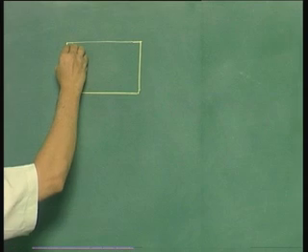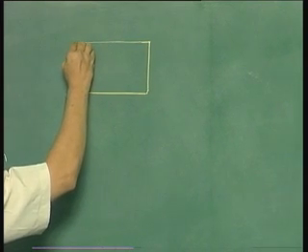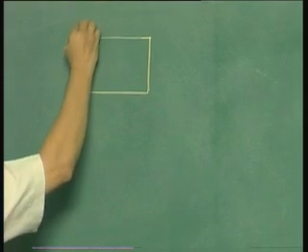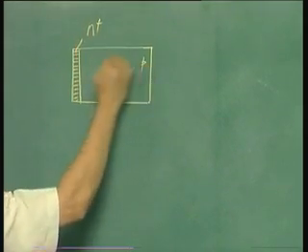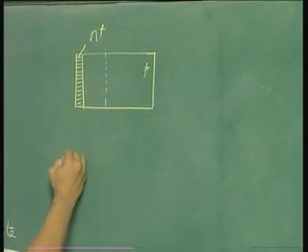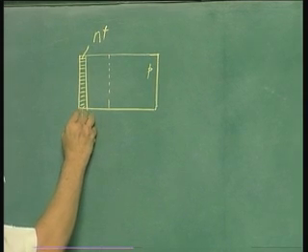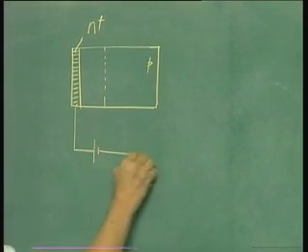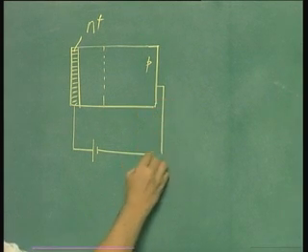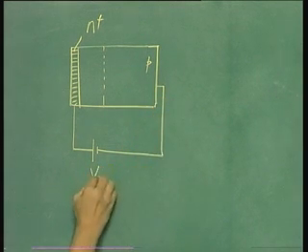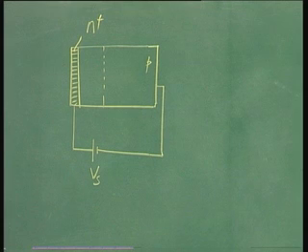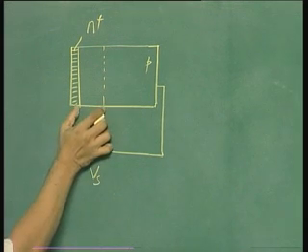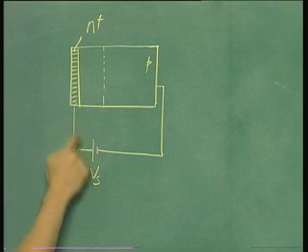So this is the inversion layer, N plus, this is P, this is the depletion layer, and you are applying a voltage which is equal to Vs. So what is the effect of this Vs? Evidently the effect of the Vs is to expand the depletion layer, because this is a reverse bias across this junction.